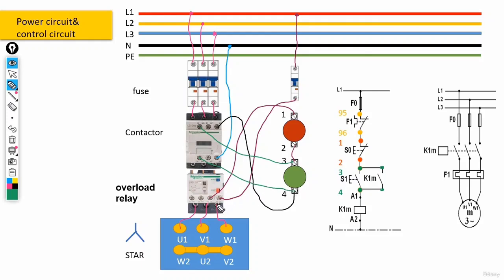Now guys, remember, in our power circuits, if the overload relay or bimetal, in other words, starts working, its contact in the control circuit would be opened, and as a result of this, the contactor would stop working. So, the overload relay or bimetal could actually cut off the contactor and as a result turn off the motor, and it could also be set in the electrical current's path in the control circuit. And well, after these contacts, 95 and 96, start working, the contactor itself again stops working.